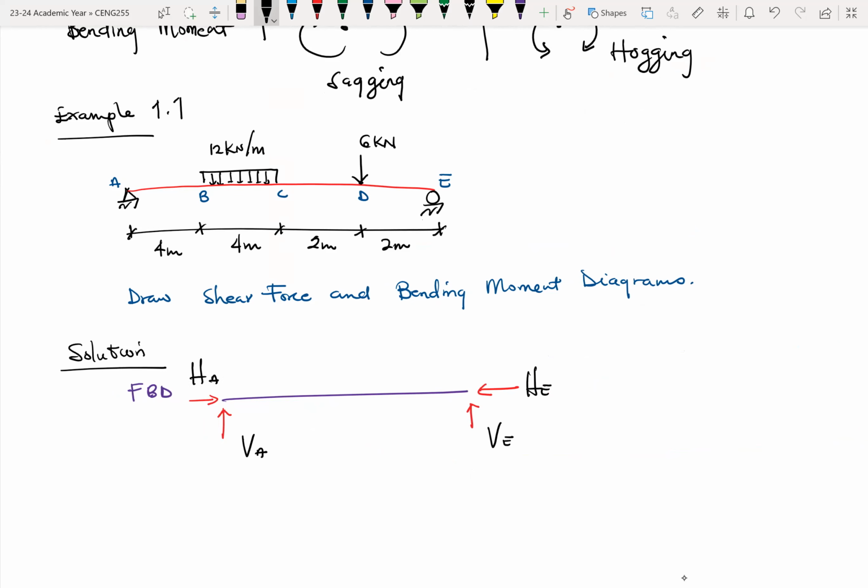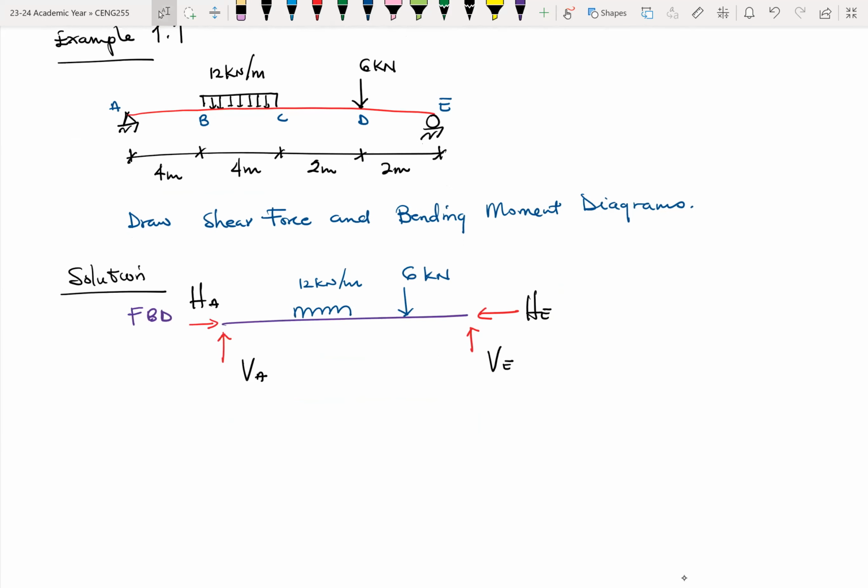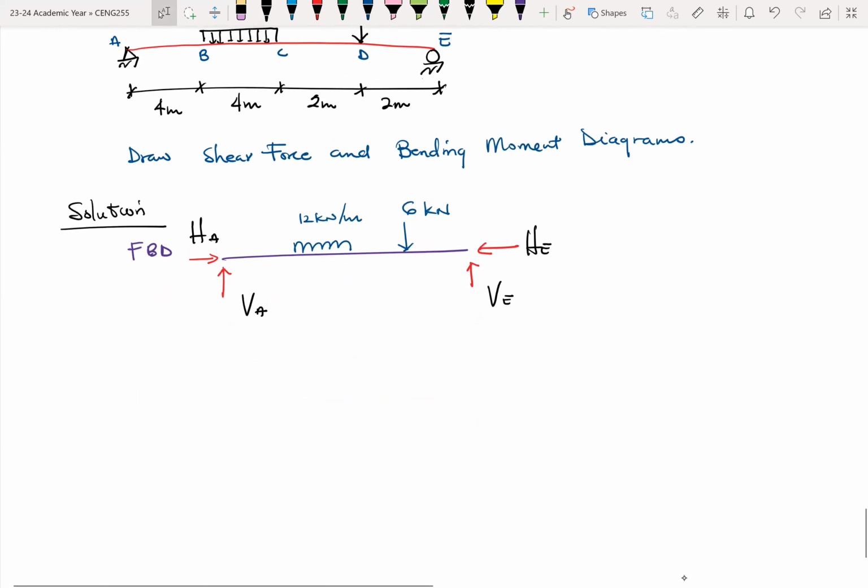So that's a free body diagram. Then you also have your loads on it. I can just do the loads this way, it's fine. So this is your free body diagram. This is to show what all the forces are. The loads are acting downwards, and we have your reaction components. So from here, you sum your loads using the equilibrium equations. Okay, so that's the plan.